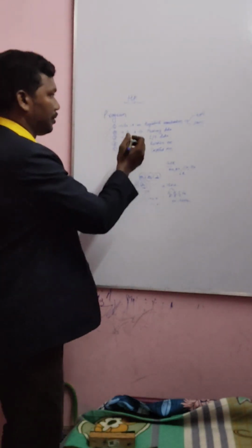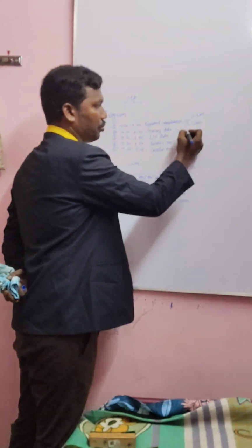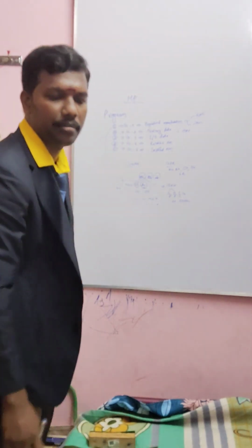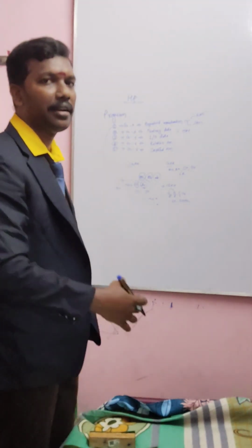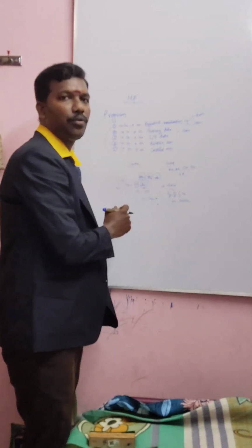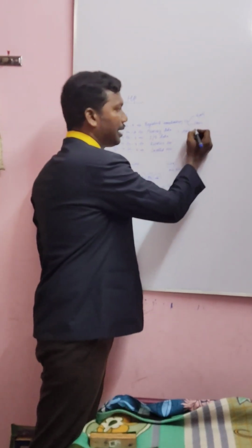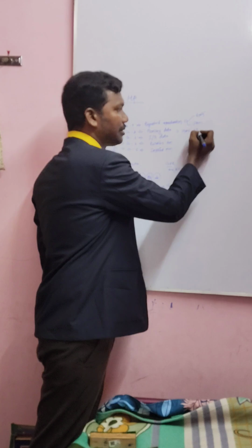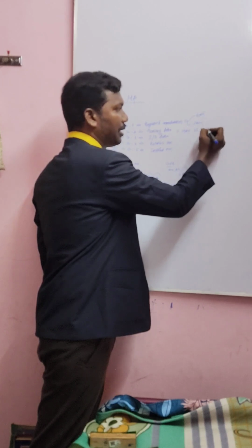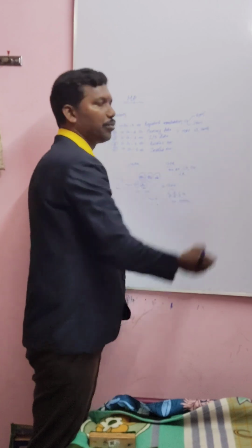Then memory data. So for memory, we have an example of MOV, a data transfer instruction, because we are discussing how we are going to access it, right? So MOV. What is MOV? Move a memory location. I take one of the index registers, SI, comma, and represent within the bracket 4200. I just took a small example.